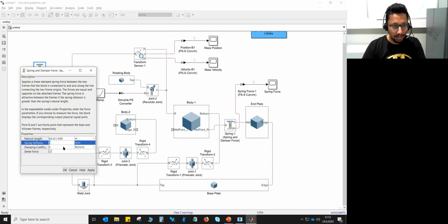For that, we use the formula omega is equal to square root of k by m, which I showed you a couple of minutes ago. We know omega, the natural frequency, is 10 radian per second, and we know the mass of the body is 1 kilogram. So how much will the stiffness be? Stiffness will be 100 Newton per meter. Be very careful with these things.